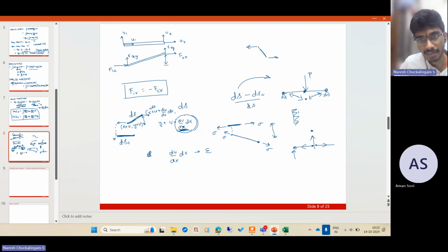So this is a structure where the elastic stiffness, the vertical resistance, elastic part will be 0, and it comes purely from a geometric thing. So if you pull it, or even better, if you take a cable and then pull it with some tension and then arrest the ends, right? You just arrest the ends of the cable. So it is under some tension.